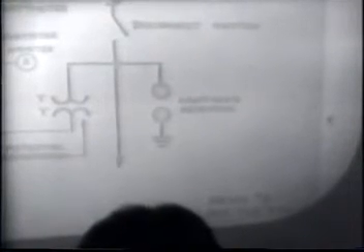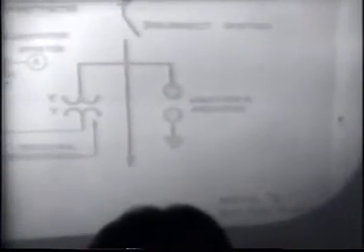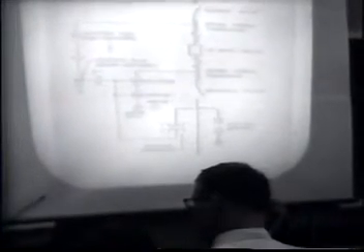The lightning arresters, represented by that symbol, have the function of diverting sudden transient voltages, such as are caused by lightning, to ground to protect the equipment within the substation, which could be damaged by this excessive voltage, and then to interrupt the 60 cycle current that will follow once the arc is established, permitting normal service to be reestablished.